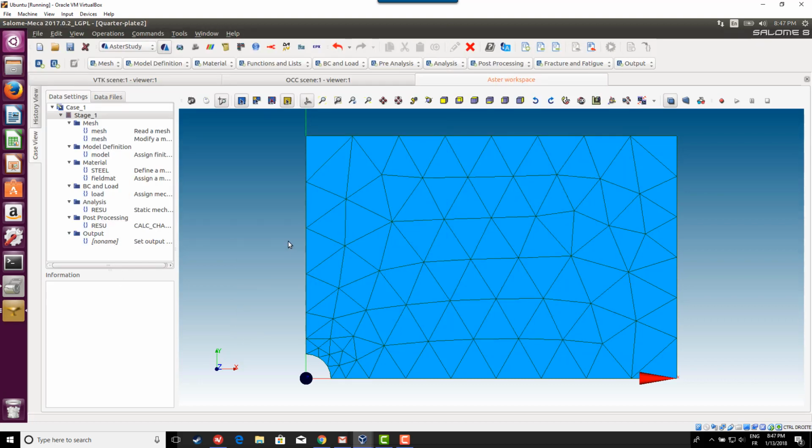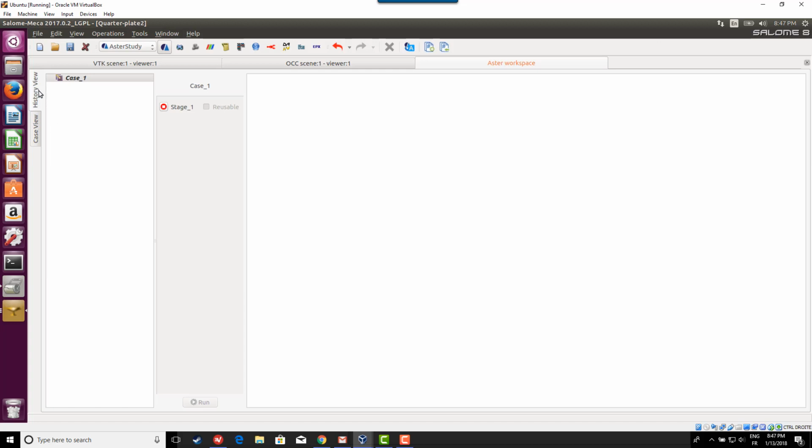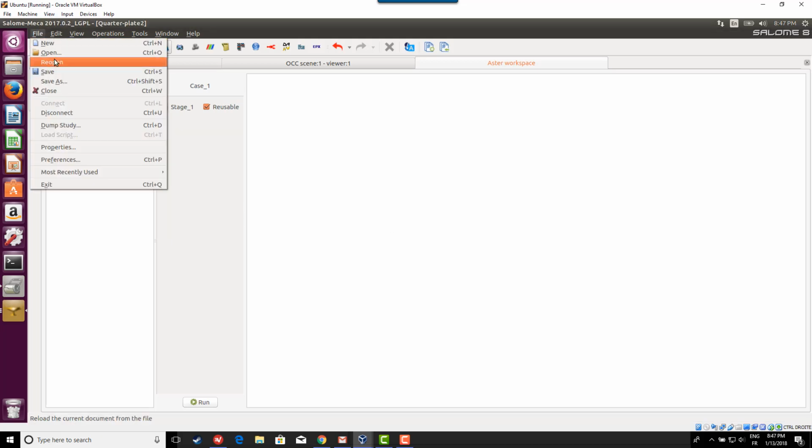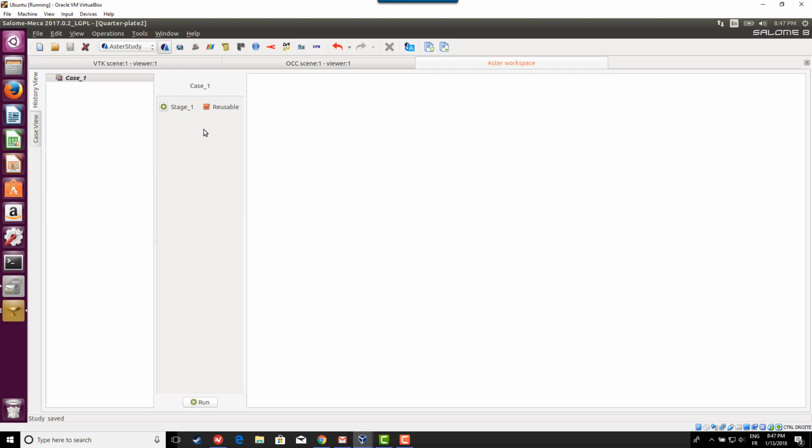Now, how do you run that? How do you get those results? Go here in history view, and okay, and here add the stage. Click on run. I should save the study because I forgot to save it. Save that.